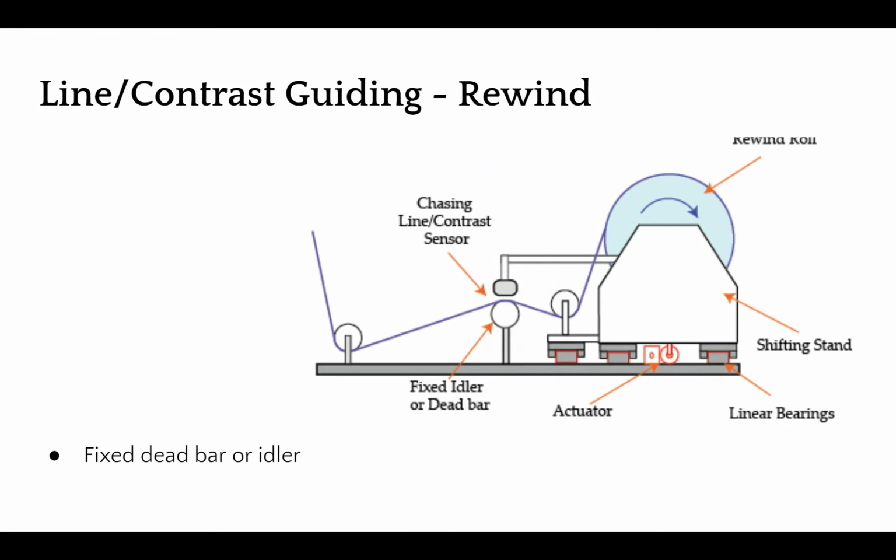Are there other filtering methods besides exponential moving average that might be more optimal? Exponential moving average, the choice of that is mainly because it is easy to implement. It's a pretty simple filter factor. That's the reason why it's more popular.